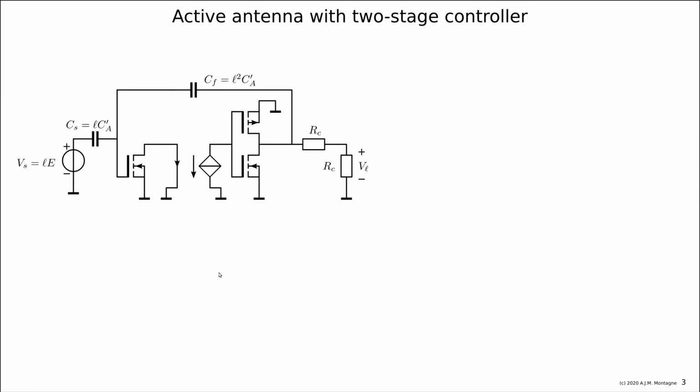But unfortunately, that controller was a non-inverting one, so we would have positive feedback instead of negative feedback. And we solved in this example this problem by adding an inverting current amplifier, unity gain current amplifier in the loop, which is also known to you as a current mirror. Today, I will stick to this concept, so no implementation of the current mirror, because we want to study the frequency compensation techniques and don't want to make things more complicated than only to focus on the frequency compensation techniques and the way to implement them.